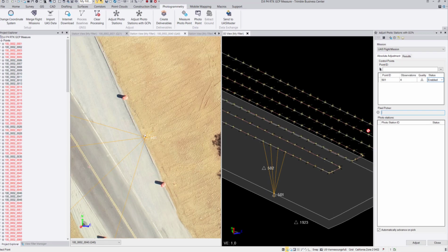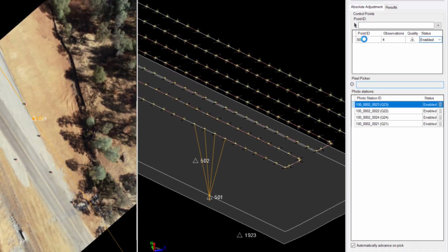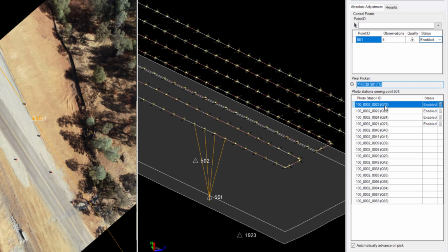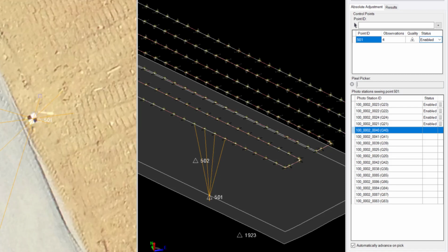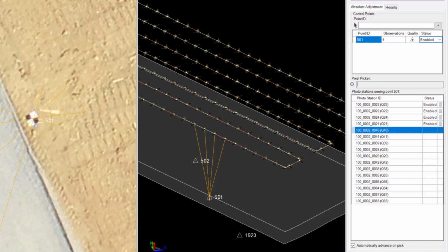We see the first 4 photos that I have measured. I can just go back to this photo here. They are all coming from the first flying line, this first strip, and this is typically an 80% overlap. So these 4 images are from the first strip. If I go now to my 5th one, and make my measurement, first of all I can see my lines of sight. I see that they are nicely cutting through and the position looks fine. So in general, the orientation of my block is good.